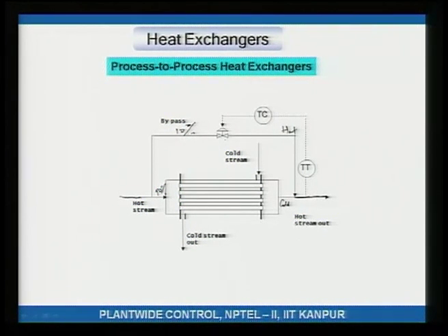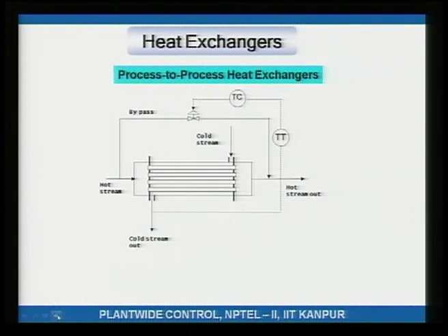If you did not have this, then we would have a problem, and I think I have discussed this problem before. So, I will leave that. Here's an indirect way of doing it. Your bypass is on the hot side, but the temperature that needs to be controlled is that of the cold side. Okay, so you are interested in this temperature, not in this temperature. This temperature can float. So, what do you do?